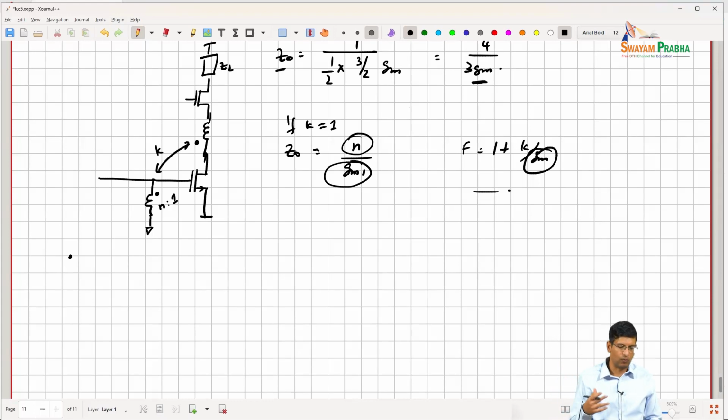So traditionally, at lower gigahertz frequencies, the way that we address this bandwidth and noise figure challenge is that we use the principle of noise cancelling, where the general idea is that I want my LNA to be matched to 50 ohms, right? So there is some circuit, let's say quite simply a common gate transistor, for example, which is providing my 1 over GM match, right?